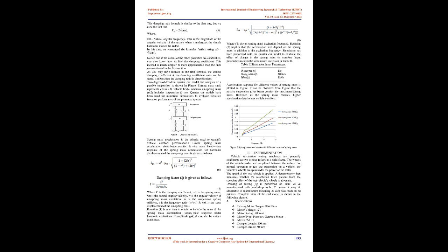8. Damping. Damping is the control of motion or oscillation, as seen with the use of hydraulic gates and valves in a vehicle's shock absorber. This may also vary, intentionally or unintentionally. Like spring rate, the optimal damping for comfort may be less than for control. Damping controls the travel speed and resistance of the vehicle's suspension. An undamped car will oscillate up and down. With proper damping levels, the car will settle back to a normal state in a minimal amount of time. Most damping in modern vehicles can be controlled by increasing or decreasing the resistance to fluid flow in the shock absorber.